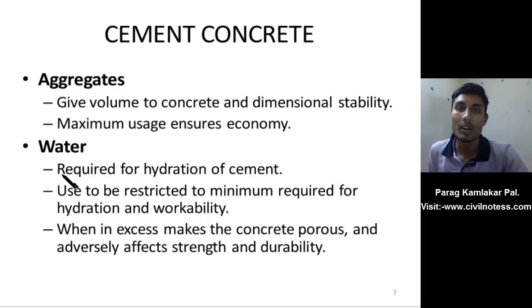Okay, now coming to the water required for hydration of the cement: it should be restricted to the minimum required for the hydration and workability. When in excess, it makes the concrete porous and adversely affects the strength and the durability, as we know.